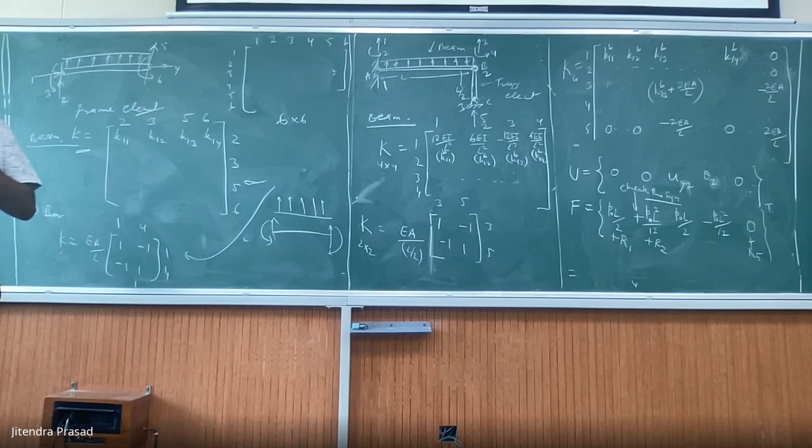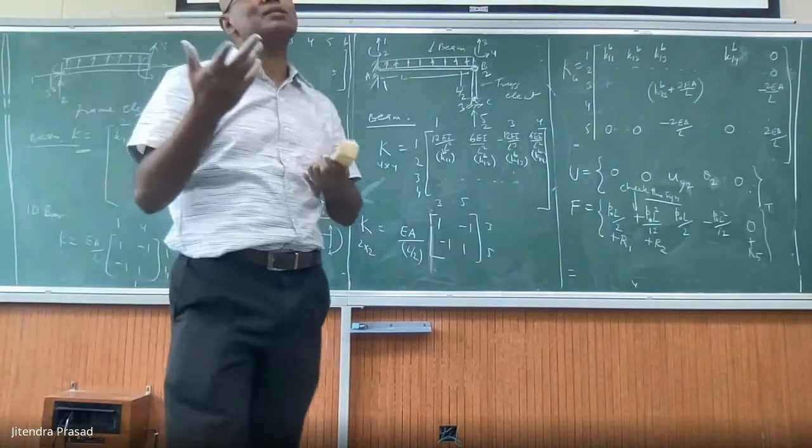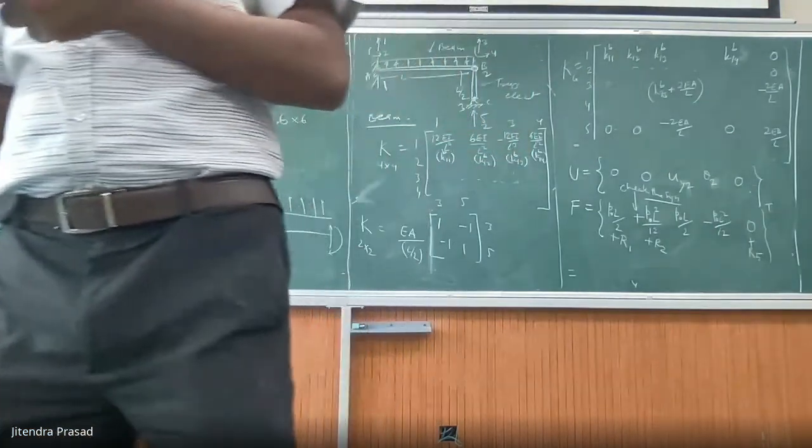If it is an axial load, you apply a truss element, right? Then if you have a force like this one, it goes to bending or shear. This becomes shear, so that gives you bending. Similarly, the force in this direction will also give you bending. This is your shear. So that means 2 bending elements and 1 axial element and 1 torsion element. You combine them together, you complete the picture. You can do it that way, because they are all independent.